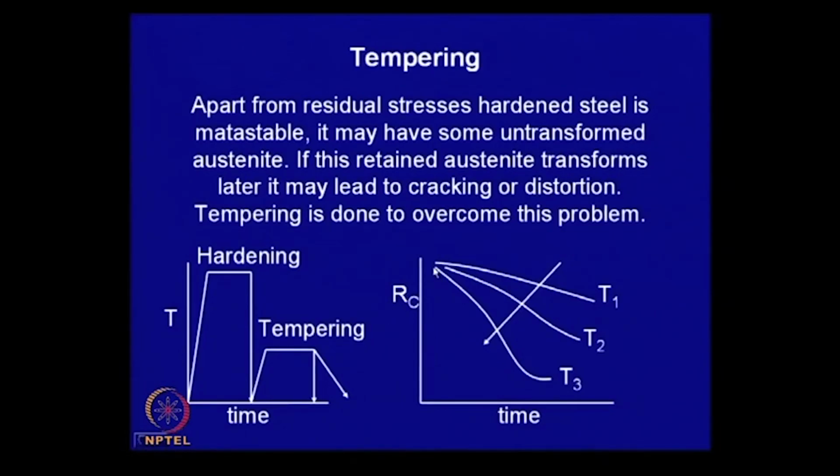What you can do is heat a series of samples, say temper at a temperature T1, and after tempering for a certain length of time you quench to room temperature, measure the hardness and make a plot. So, this gives the kinetics of hardness change at temperature T1, and you will find if you increase the temperature, the rate of that hardness decrease becomes faster.